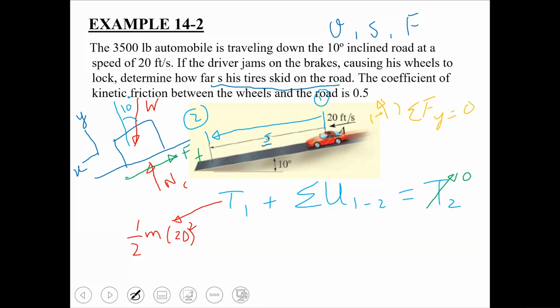सर वर्टिकल फोर्सेस जो है वो इक्वल होंगी ना, तो So I am basically applying the equation of motion. देखिए technical terms में बात किया करें. So I am applying the equation of motion on this particle along the y-axis. So summation fy equal to 0 since the particle is moving along the x-axis, जो मेरी x-axis define हुई हुई है, that is along the incline. So summation fy would be equal to 0. That will give me NC to be equal to W cos of 10. ठीक है. So W cos 10 मेरे पास NC आ जाएगा. अब मैं फोर्स ऑफ फ्रिक्शन जो है वो निकाल सकता हूँ.